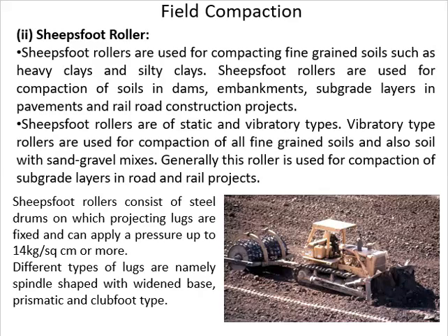Mainly for rail projects and subgrade layers in road projects. The efficiency of this roller depends on the gross weight of the roller, contact area of the projections and their spacing also. The pressure is maximum when a foot is vertical.